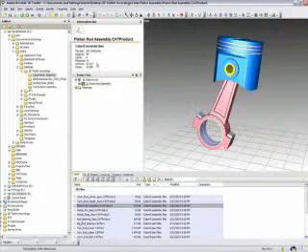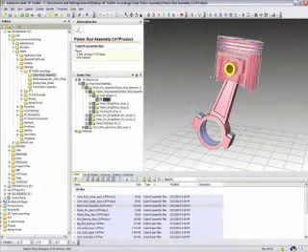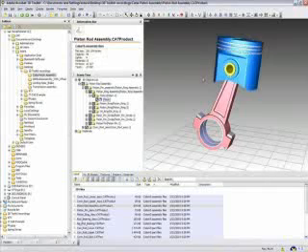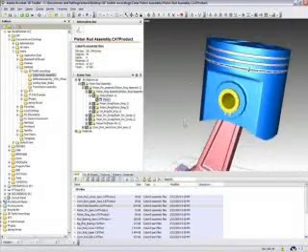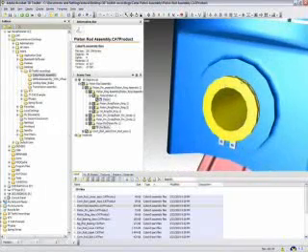You can see this and other attributes in the information bar. The information bar displays the number of objects, lights, materials, vertices, and faces in the current scene. By selecting the object, you can see that this particular piston is made up of a series of polygons that form the three-dimensional mesh. When I zoom in on this object, you'll notice that this piston pin is coarsely tessellated. In other words, what should be a round circle is faceted.